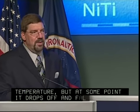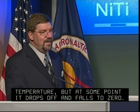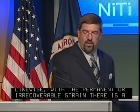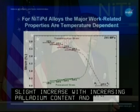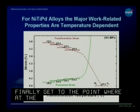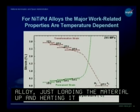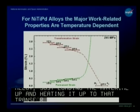Likewise, with the permanent or irrecoverable strain, there's a slight increase with increasing palladium content. And again, you finally get to the point where at the 46% palladium-containing alloy, just loading the material up and heating it up to that transformation temperature causes the material to fail. So if you want, go to the next slide, please.